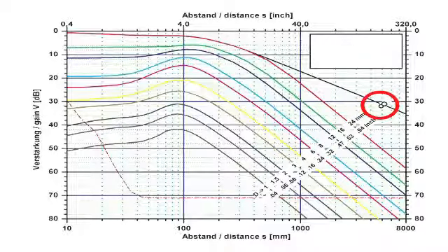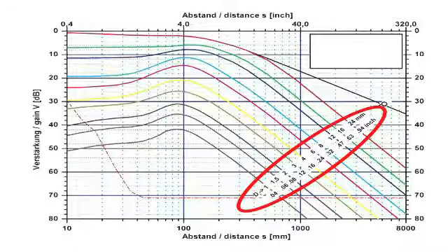Additionally, the noise level is also shown on the DGS diagram. This noise level tells the user the difference in dB between the echo amplitude of a given ERS and the noise level at this specific depth. As described, the determination of the equivalent reflector size is based on the comparison of two echo amplitudes. The echo from an unknown reflector is compared with the echo from a known one, or a reference reflector.